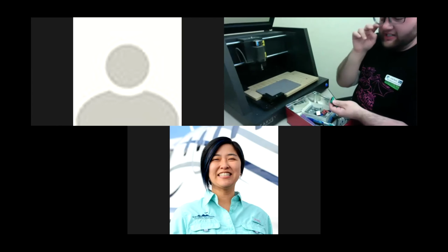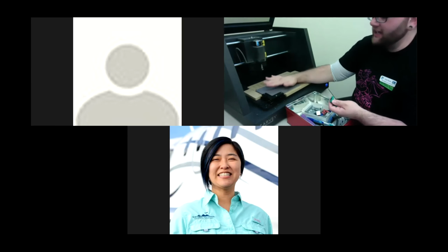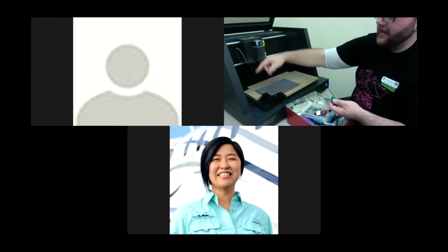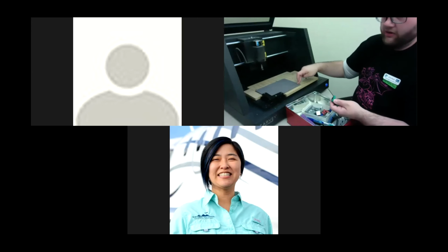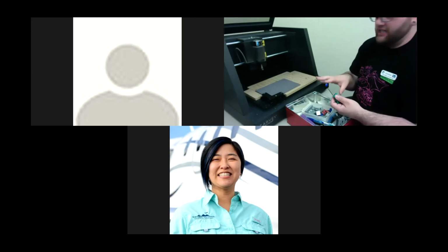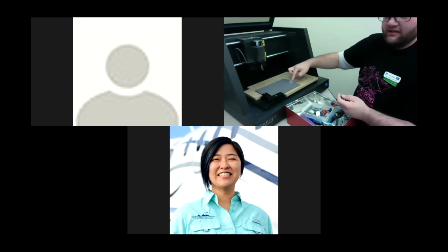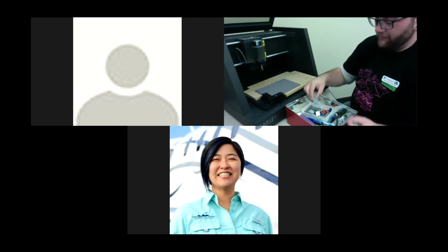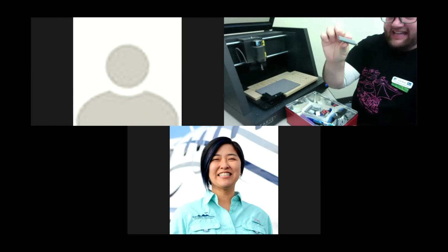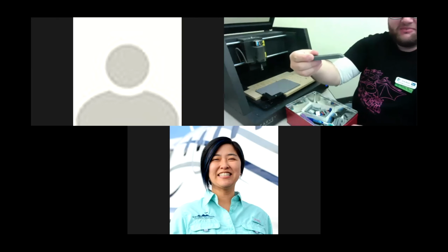And so we actually need to put the 5 screws into the board. So that's how the material is held down. It's held down with screws. So there's 2 on the smart clamp, and then we need to have 1 on each corner to hold the material down. And there's also screw holes in the board on strategic locations that will allow you to then use these ramps to hold the material down. What's really cool is most of our ramps are 3D printed, because it only came with 5 and they got destroyed. So all of these are 3D printed, which is pretty cool.